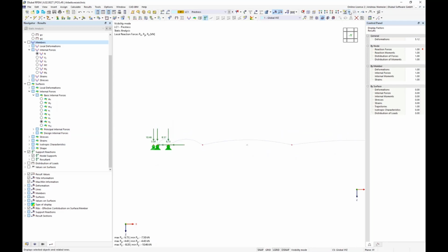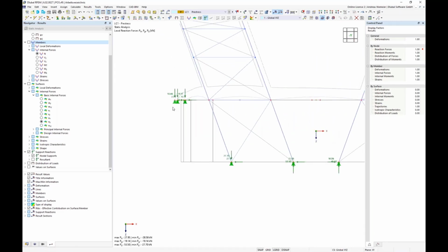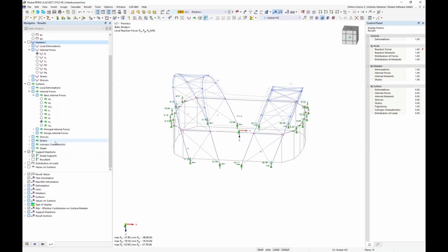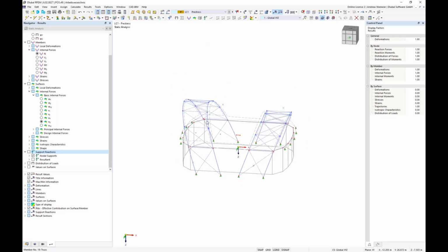And if you see everything, yeah, the membrane is hanging on these cables and giving forces to arcs and to these supports. So far, we have now defined a shape consisting of these 2 arc pairs, and we are now in the situation to start with our regular structural analysis job. That means we have to check if the structure can sustain snow load, self weight, wind loads, and so on. And for this we have to define load cases.